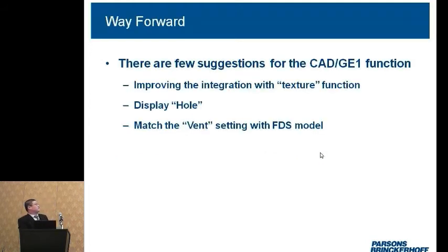I found out that the texture can be integrated in the CAD, but it's not fully integrated now. Sometimes the texture will be shifted. Also, the obstruction holes can't be displayed in the CAD. And the other one is that the vent settings in the FDS model and the CAD model are not fully matched.